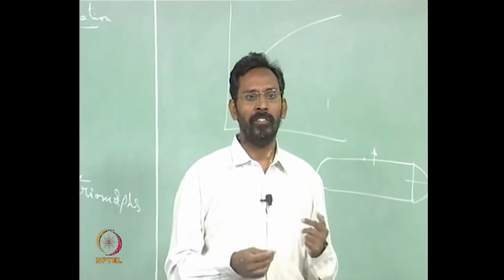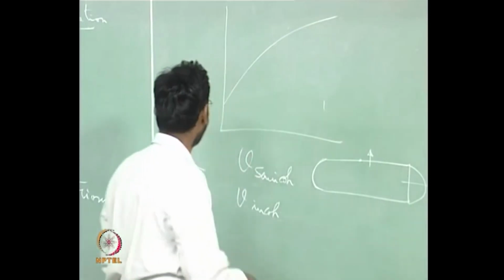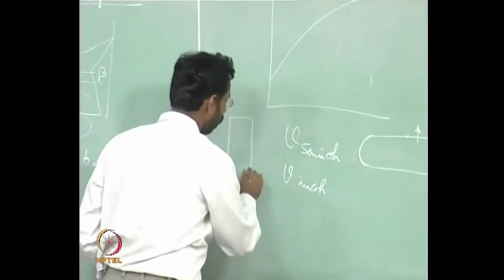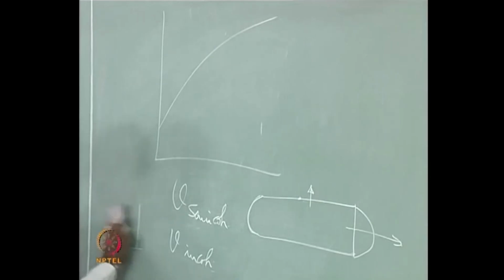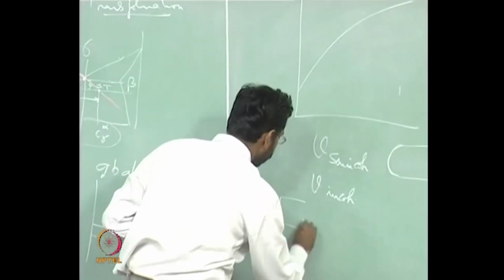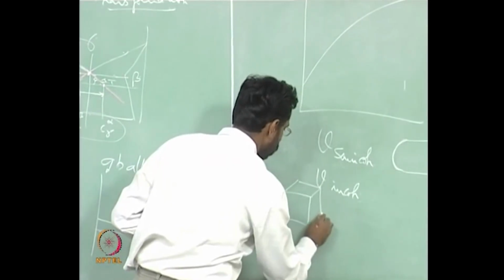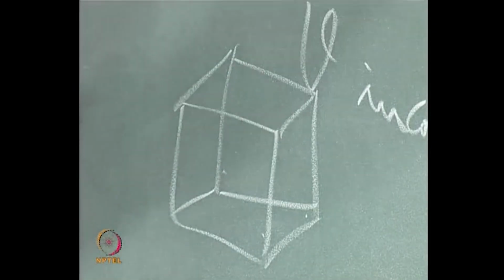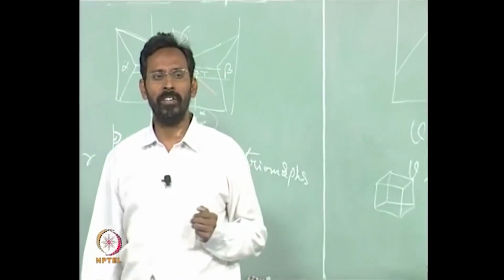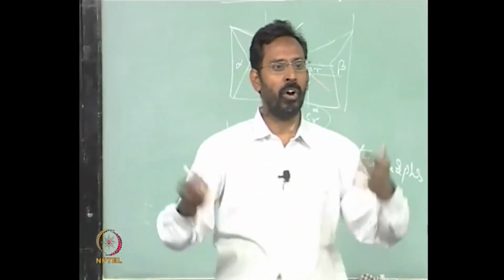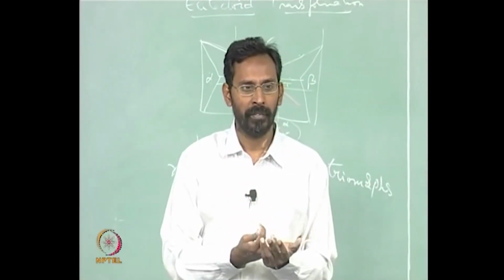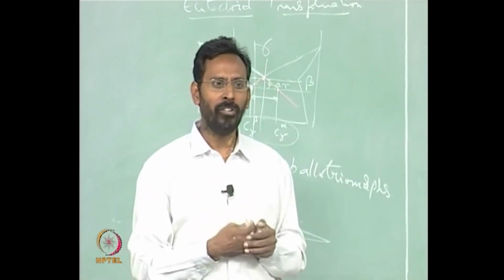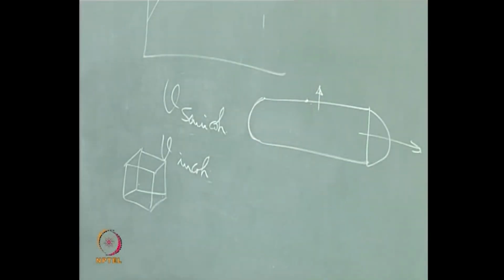That is because whenever you look at any precipitate, for example a nucleus has formed something like this, or maybe initially you imagine it is like a cube, because silicon let us say is cubic in nature, diamond cubic. So some nucleus has formed, this nucleus has to now grow. The growth depends on the rate of atoms joining from the liquid to that silicon, and not only does it depend on that, it also depends on which plane needs fewer atoms for it to grow.